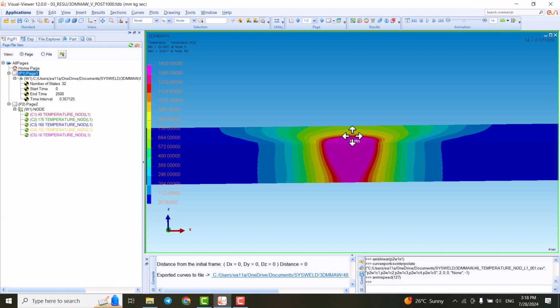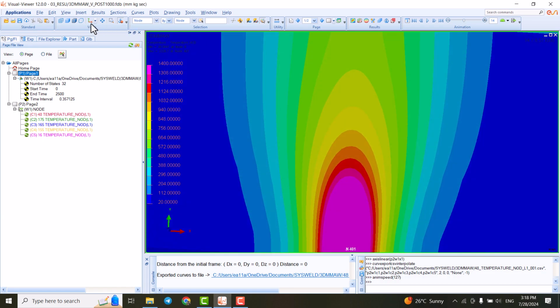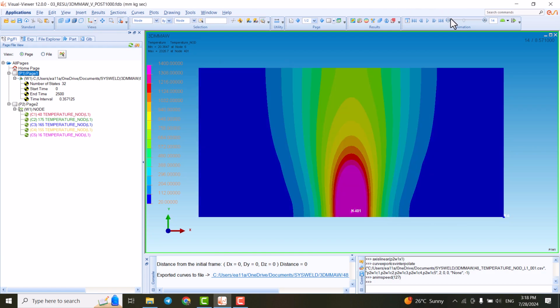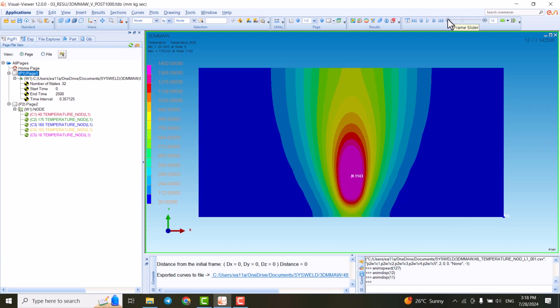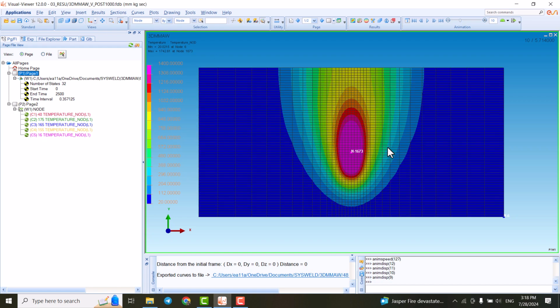And see what happens if we want to go from a path and plot our results in a path. So we go to the top view, and we can say, let's say here, which is in the middle. So we select this one, as we can see the nodes on the mesh here.